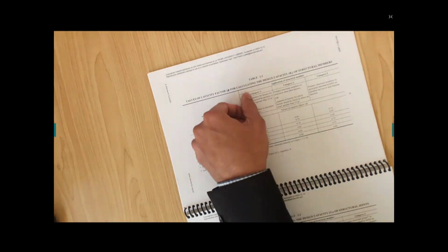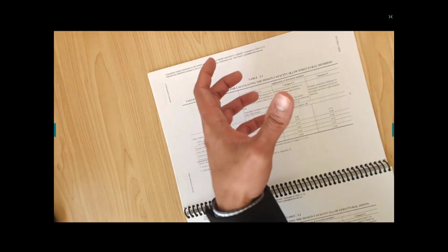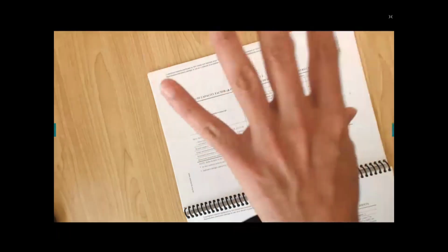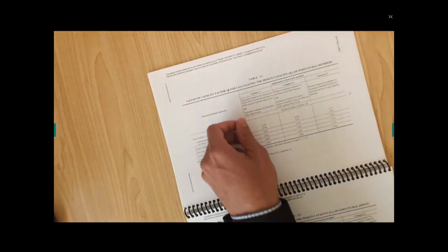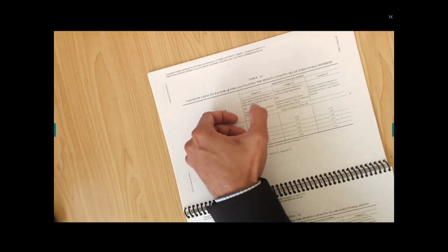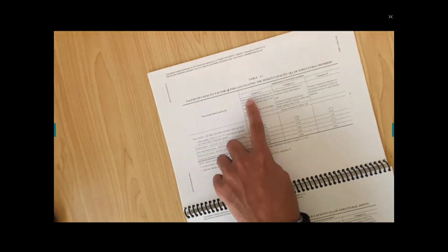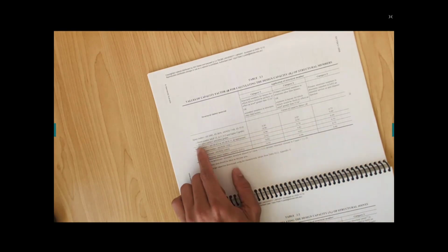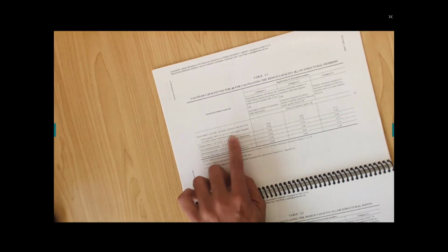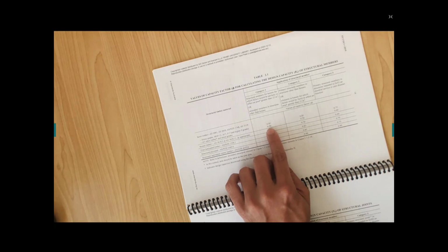So in here we are going to do category number 1. You know the stairs, right? Stairs are not critical. If the stringers fail, it will not take your whole building down, right? So you can have just less than 25 square meters of area affected. So we are in category number 1. We are in the F14. All other timber, we don't have F14 here, so all other grades. So we take phi equal to 0.9.